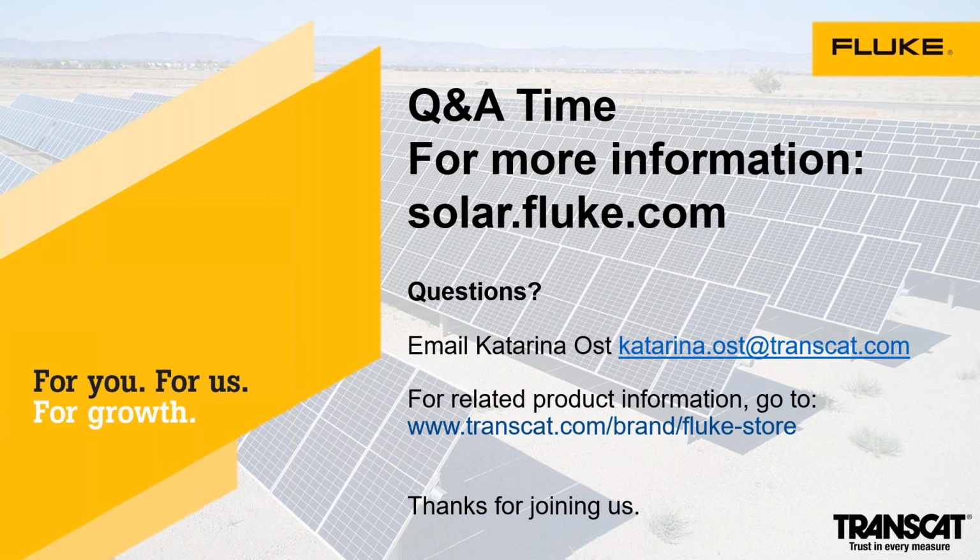You know, we've got these things going through thermal cycles, so heating up, cooling down, especially as they're in somewhat harsh environments. So retorquing those terminals is always a good idea. Now, the problem I've always had, and I haven't figured out a solution to, is how to identify over torquing. That's really hard to do because you don't really have a reverse torque meter, and you don't want to continue to torque something past its torque setting if it's already over torqued. So that's a challenge that I've not yet found a solution to.